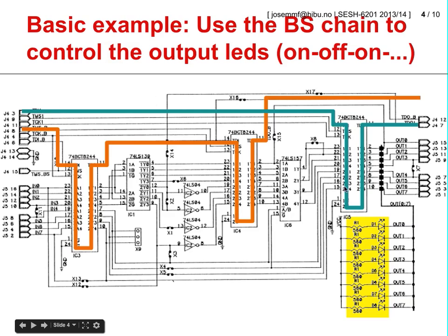Now, please recall that our demonstration board comprises 2 boundary scan chains, and the LEDs are connected to the outputs of the device that is placed in the second boundary scan chain. Since the current set of test commands that are proposed for your coursework does not include one test command to switch from one boundary scan chain to the other, we will have to assume that the appropriate physical connections will have been established beforehand.